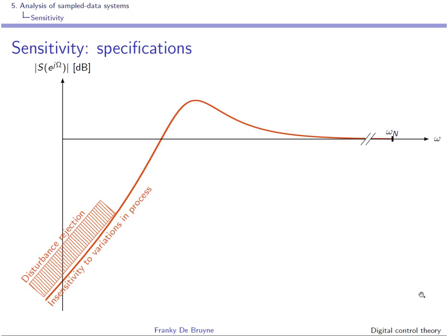If we look at the top part of the Bode diagram associated with this sensitivity function, so we look at the gain or the module. Here it's expressed in dB. Well, you can kind of see here omega here is the discrete frequency, so I could put omega over here, right? And you look up to pi. Remember that omega, the discrete frequency, is related to the analog frequency by this relation.